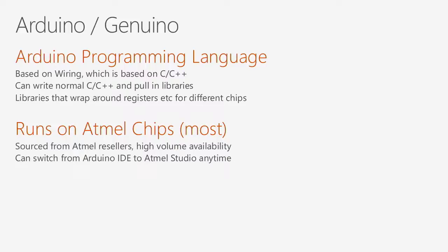And the idea is that the Arduino programming language kind of hides away the nasty bits from you, like the makefile and the registers. Okay, so on the microprocessors, if you want to set a particular pin to output, what you gotta do is look up the data sheet to find the actual register that this setting is in, and you have to find a bit value that that pin corresponds to, and you have to write literally zeros and ones into these registers to turn them into input and output.